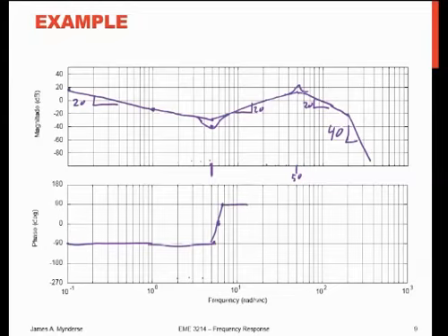and it flattens out. I'm going to draw the effect of the complex pole and the first order pole separately because they kind of overlap. So I'm going to draw a dotted line here out to 42, that's right there. And that passes through here and there, and that would be the effect of that complex pole.